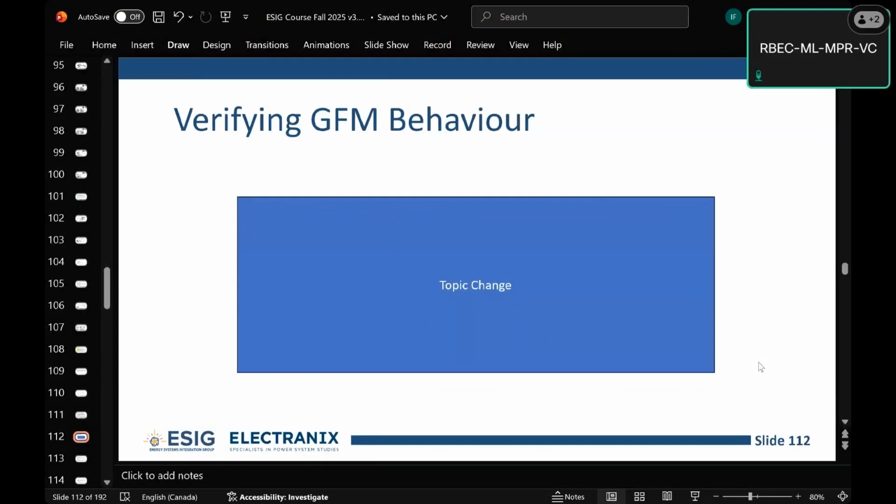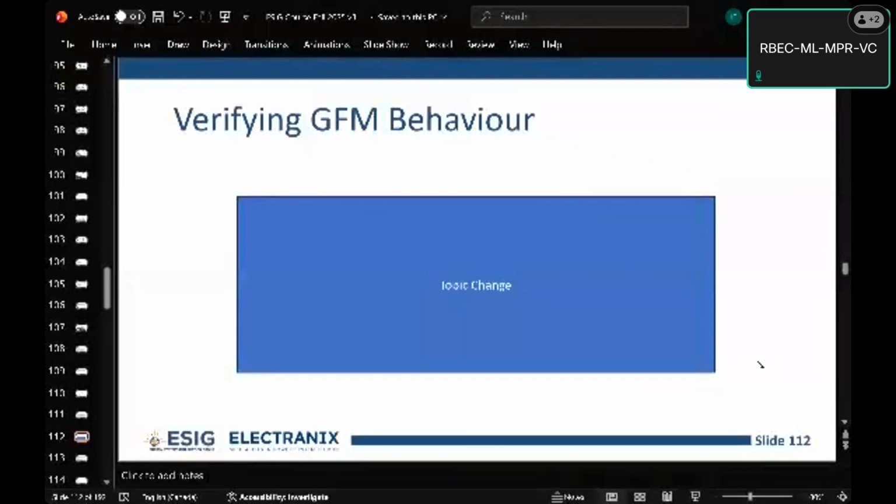I think so. My information that I've gotten on this is that what's happening with the batteries with a grid forming controller is you're cycling your current potentially all the time, or if it's damping oscillations, you're moving your current in and out. But that doesn't actually move the state of charge on the battery at all. And so moving current in and out of the battery within its ratings is fine. Moving the state of charge significantly in the battery will degrade its life. That's my simplified understanding of battery chemistry. I've been asking this question and nobody's telling me it's a problem. But it's a fair question, I think.